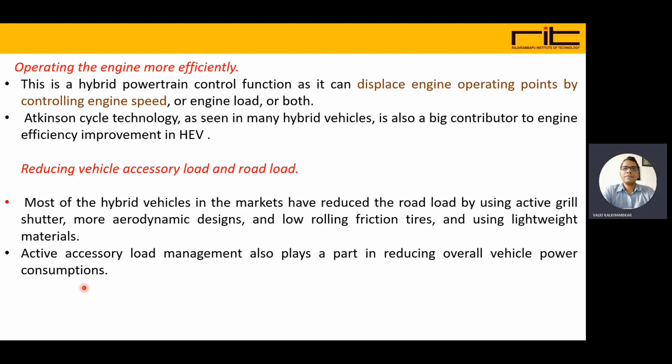Next, operating the engine more efficiently. This is a hybrid powertrain control function, as it can displace engine operating points by controlling engine speed or engine load or both. For example, Atkinson cycle technology, as seen in many hybrid electric vehicles, also contributes to engine efficiency improvement.